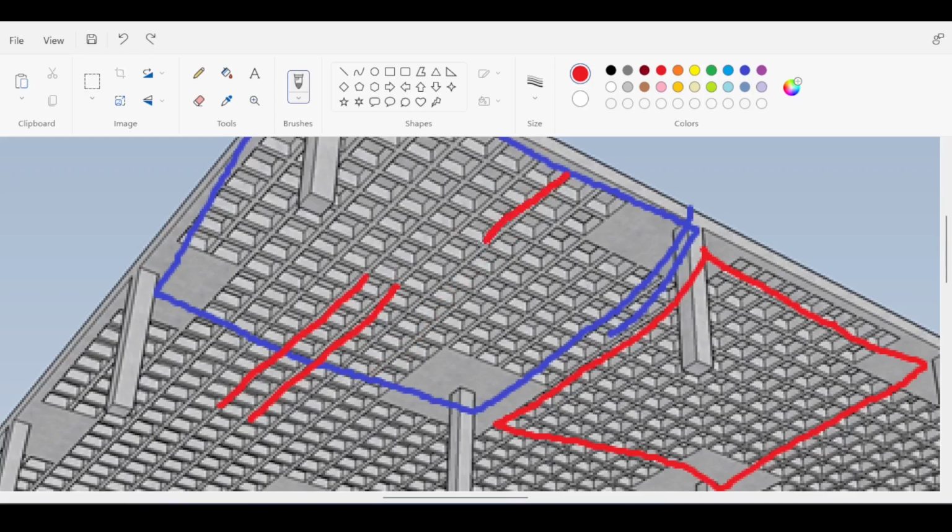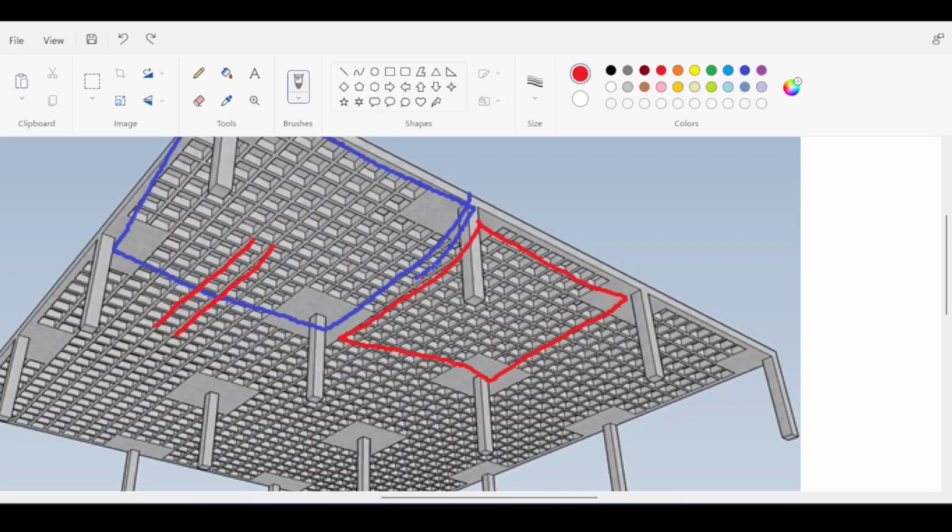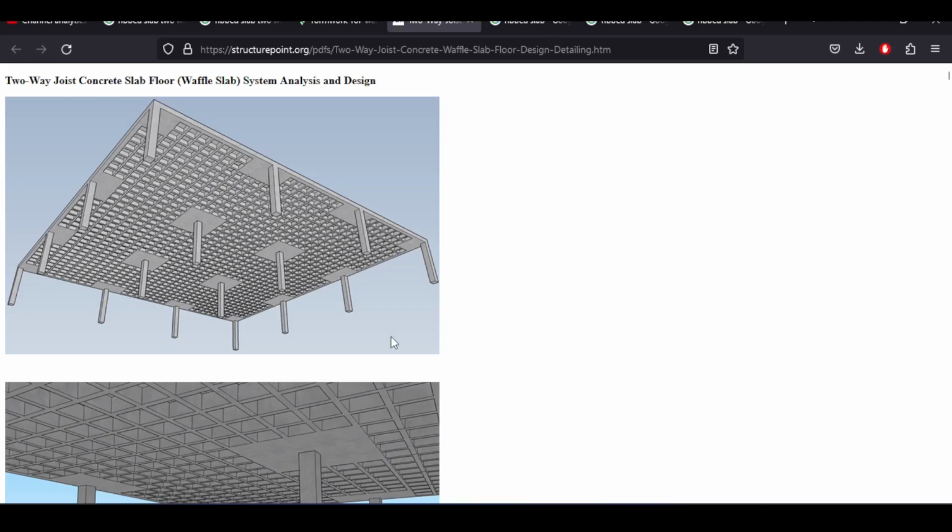So, for example, if you misalign those ribs, then this rib works independently of the rib beside it if it's misaligned. And you notice that in all ribbed slabs, the ribs are actually aligned, or we are trying to align them as much as possible for different plates. So let's take a look at the pictures.